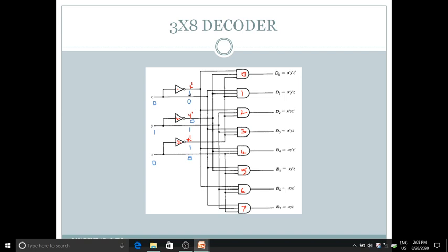Now you can write the inputs for each and every AND gate, the 8 AND gates, and after writing the inputs we can easily say what the output of each AND gate is. You can see that for the 0th AND gate, one input is z bar, which is 1, and y bar is 0. And what is the third input?